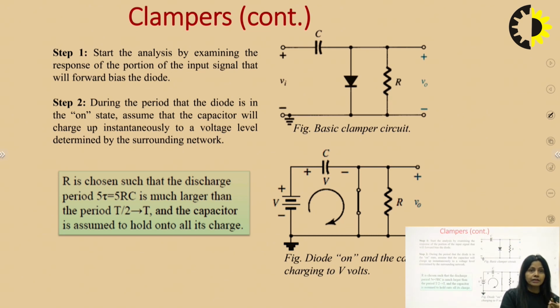So step 1 consists of 2 calculations. First you get the capacitor charge or capacitor voltage, and then you calculate the output voltage. Now go to step 2, with the diode reverse biased, and let the voltage on the capacitor VC be the same.